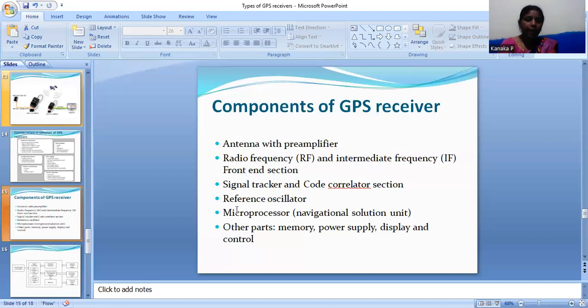A total station is operated through the control panel, which consists of a keyboard and a multiple-line LCD. A number of instruments have two control panels, one on each face, which makes them easier to use. Next one is software applications. The microprocessor built into the total station is a small computer whose main function is controlling the measurement of angles and distances. The LCD screen guides the operator in taking the measurements.